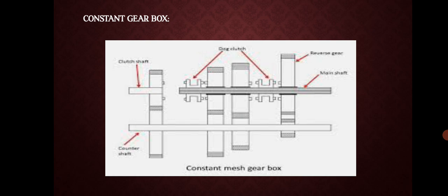When the gear lever is engaged, the coupling devices, which have internal splines, are mounted on the external spline of the main shaft, moving from one side to another to lock a free gear on the main shaft. Thus, the main shaft gets drive through gear and coupling unit.